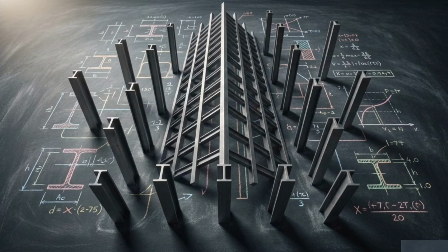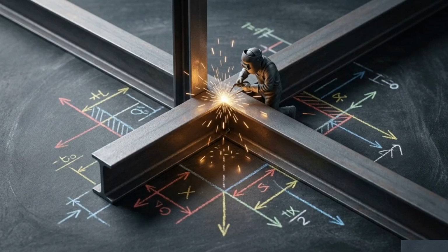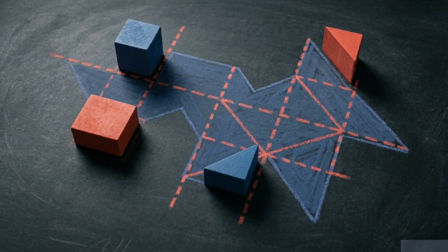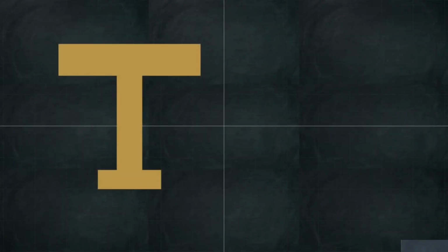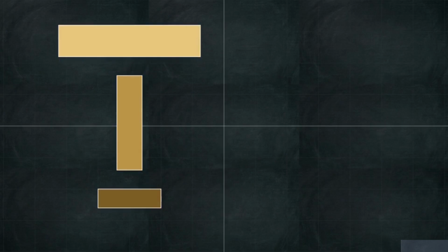But physical infrastructure is not constructed out of continuously curving calculus boundaries. Structural engineering requires a discrete tool to rapidly analyze the standard steel beams and concrete profiles used in modern design. To bypass the need for continuous integration on every component, statics relies on the method of composite parts. This relies on the principle of superposition. Instead of analyzing a complex cross-section as a single curve, engineers fracture it into primitive geometric building blocks. Primitive shapes like rectangles and triangles have pre-calculated local centroids. Their geometric centers are established constants.